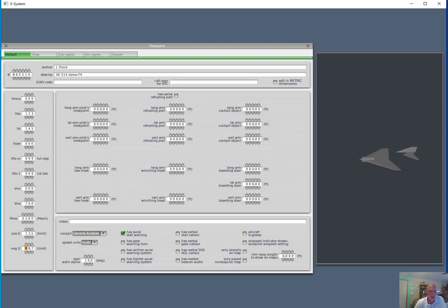And then in this column here, we're going to tell it where the pilot viewpoint is located. So this creates the view out of the cockpit. The pilot is located 1.9 forward of the datum because he sits in front of the apex of the wing. That's our datum. Lateral arm is 0 and the vertical arm is 4.5. Notice you could put a tow hook here on the airplane, all kinds of aerial refueling ports, other options, objects here can be added in. And I think we've covered everything on the handout there, so we can close this out.